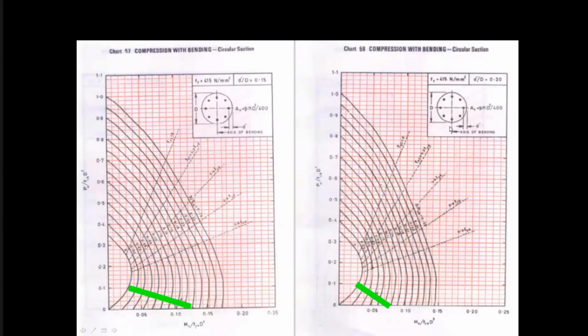So my first request when you're choosing a cross-sectional shape is don't choose circle anymore in this country. Make it square if you can and slightly marginally rectangular. A ratio of about 0.8 or so is really good if you're making a column pier. If you make a wall pier, of course, the ratio will be different. But for a column pier, no circles at all, please.